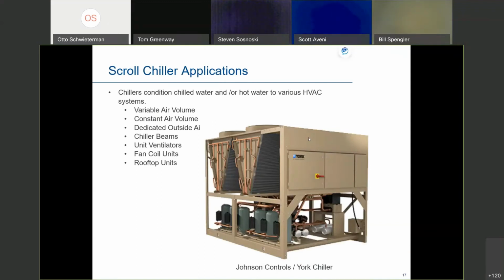Most things that you use a compressor for in a compressorized air unit, you could get your cooling out of a chiller instead of a direct expansion unit with compressors on the specific unit. So we're going to have our compressors here chilling the water, instead of compressors providing refrigerant inside the coil on a unit to condition the air.